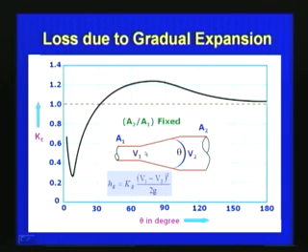Depending upon how much the expansion angle is, you can see that the loss coefficient is initially coming less, starting from about 0.7 and going down, and then when the angle increases it is again increasing, and finally it becomes constant like this. This is obtained through a large number of experiments. This gives the loss coefficient K with respect to the angle theta.